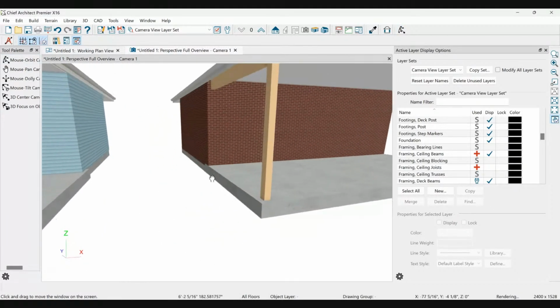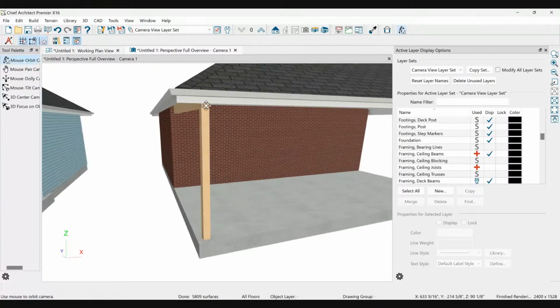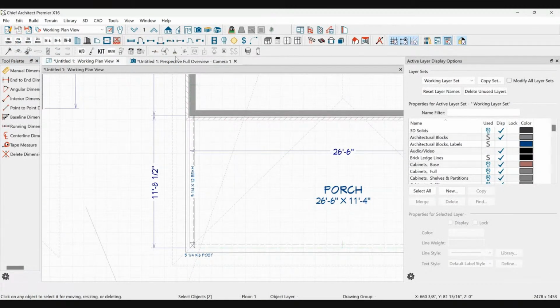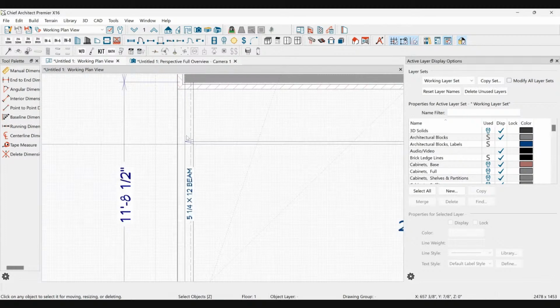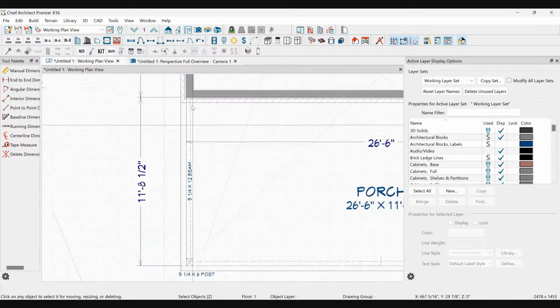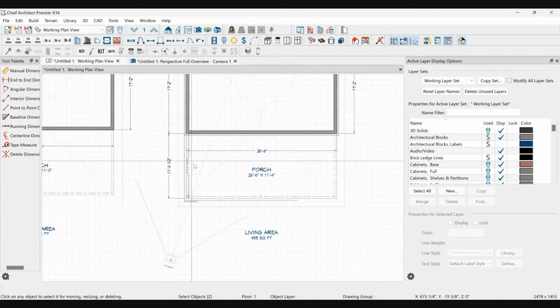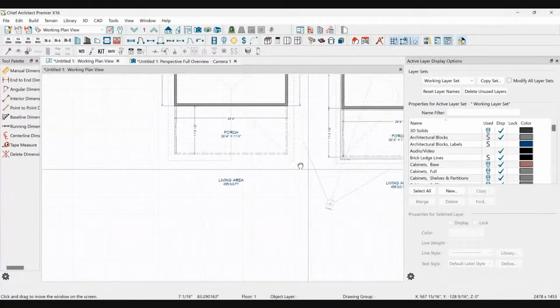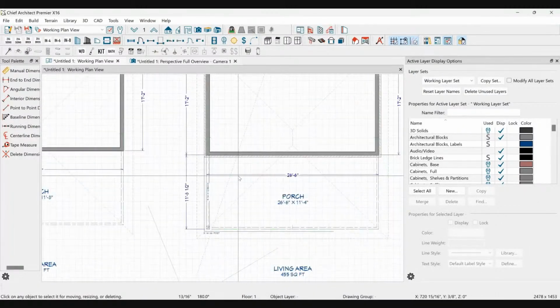There are other ways to basically adjust the post and adjust the framing, but then you start to get into more difficult rafter framing, because now if you move the post or move the beam, you have to cut the bird's mouth differently for the rafters that are on the porch. We just don't want to do that. We like to use all of our nice easy numbers.